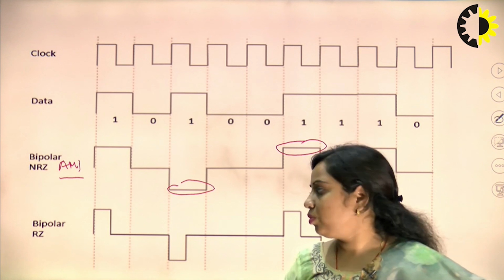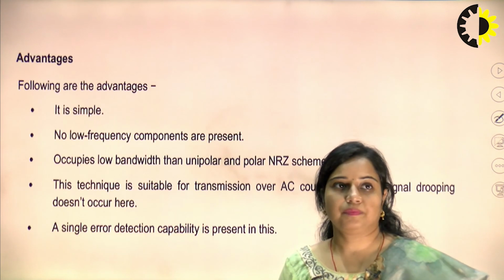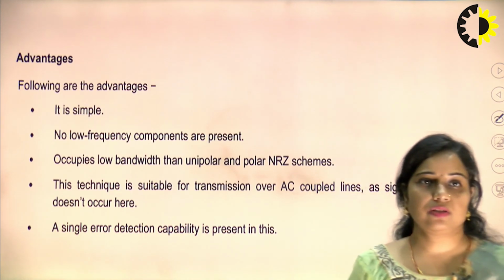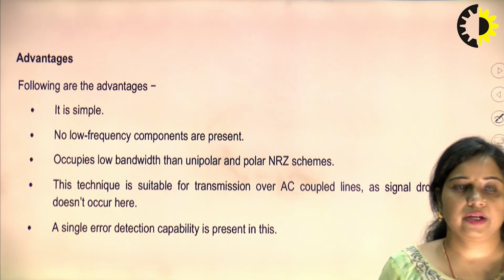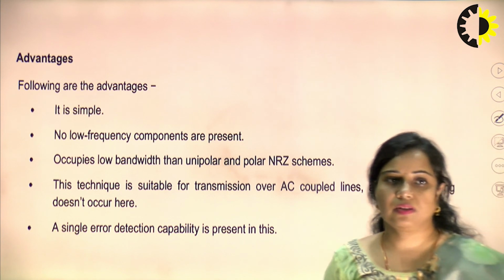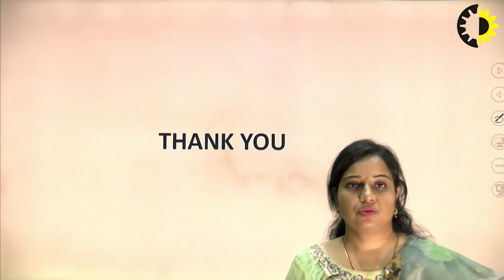In the same manner you can make the RZ waveform. These are the advantages: it is simple, no low frequency component is present, and a single error detection capability is present in this case. So, this is all about today's lecture.